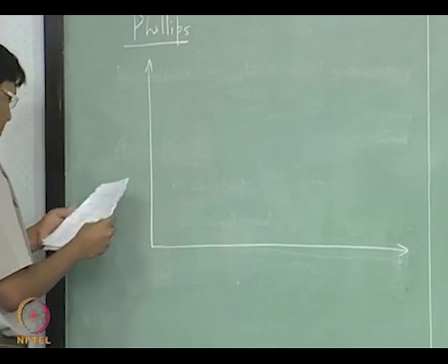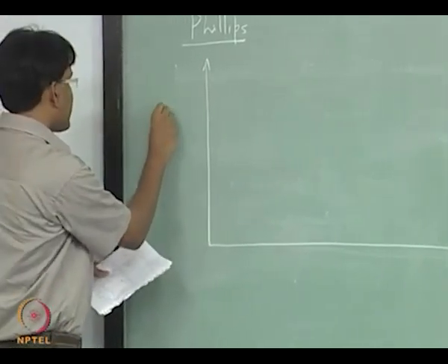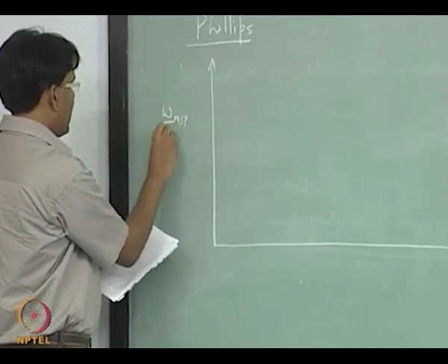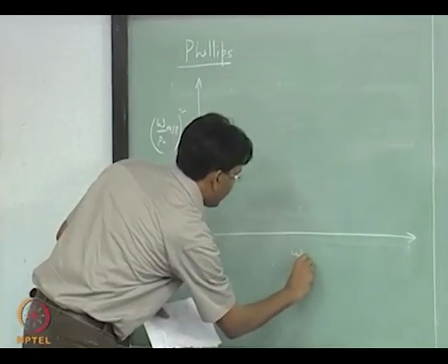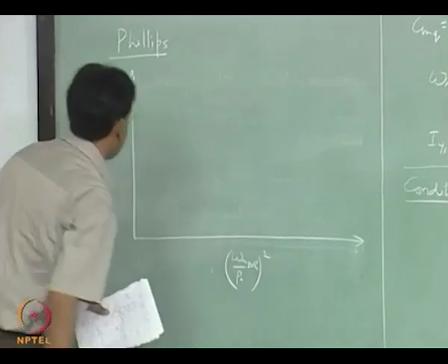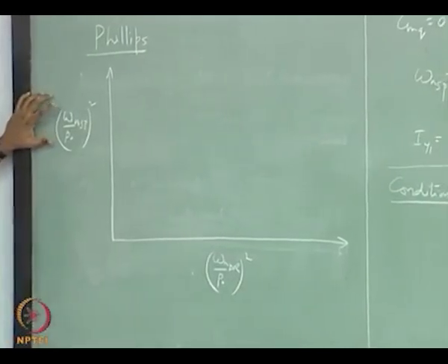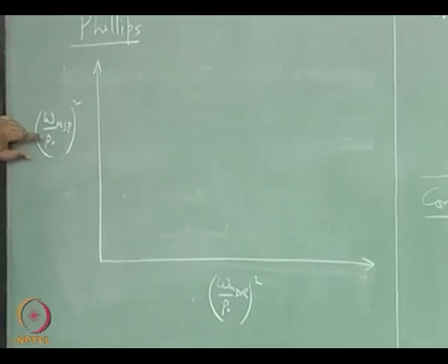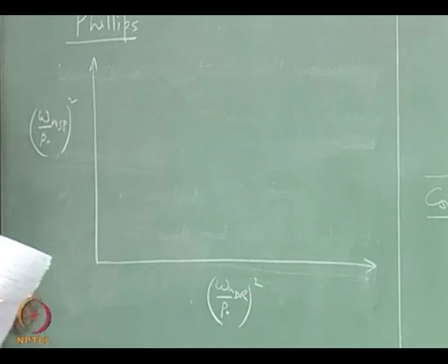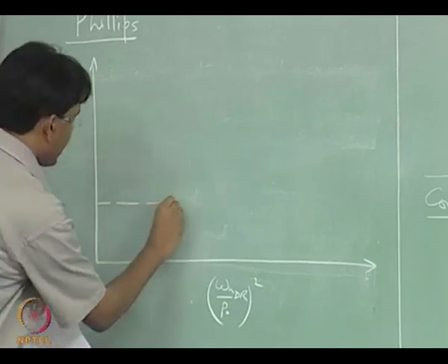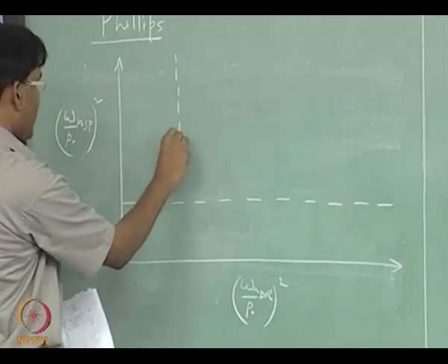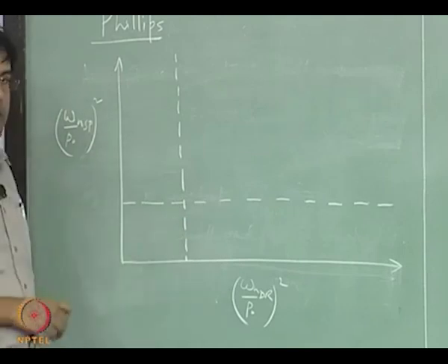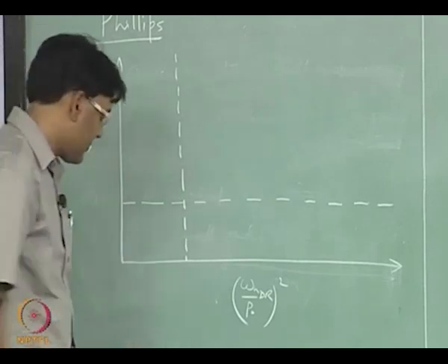So, this boundary is defined in terms of this ratio, of short period frequency over the steady roll rate squared and Dutch roll frequency over steady roll rate squared, using the conditions that we have based on the inertia terms and these frequencies.